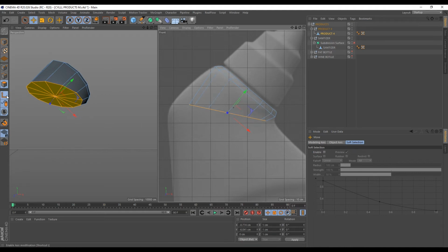So once this axis mode is selected, you can only move your gizmo. You can't move your object or any other thing in your scene. So this is how you can set your gizmo to wherever you want it to be set. So with the axis mode selected here, let's rotate this gizmo to fit how we want it to fit. So let's hit R on our keyboard to enable our rotate tool. Then let's just rotate the gizmo this way to follow how we rotated the object.